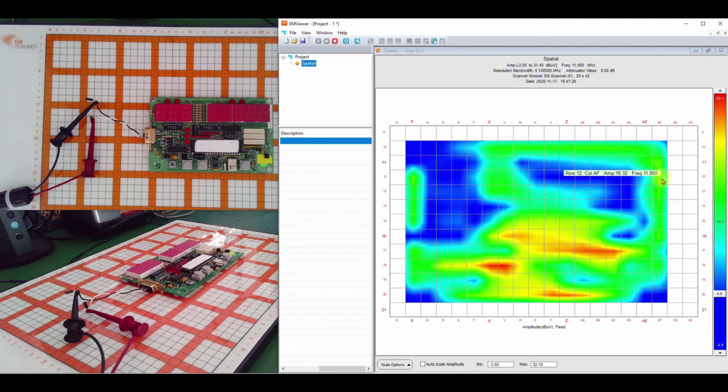This is something that you can try in your designs with changes in your hardware, trying different components, for example, different values of capacitors, or for example, changing the software that is running in the microcontroller to see the effect in the emissions from your product.